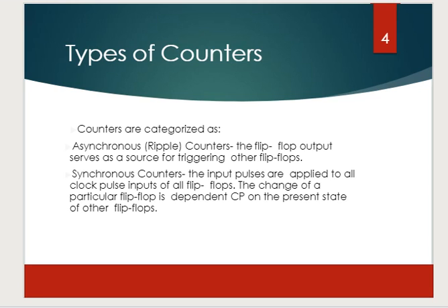If we talk about the synchronous counter, because our question is related to the synchronous counter, we're going to discuss this in detail. First, let us discuss the functionality and how it works. The input pulses are applied to the clock pulse input of all flip-flops. The change of a particular flip-flop is dependent on the clock pulse and on the present state of the flip-flop. There is a basic difference: in a synchronous counter, a clock is simultaneously provided to all the flip-flops of the counter. That was the main difference between asynchronous and synchronous counters.